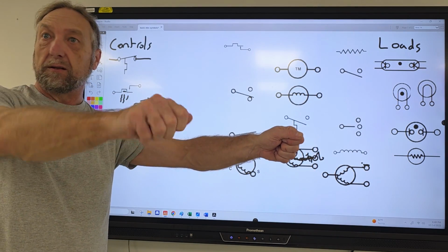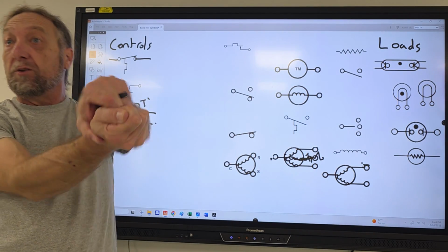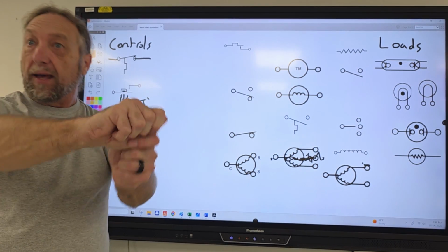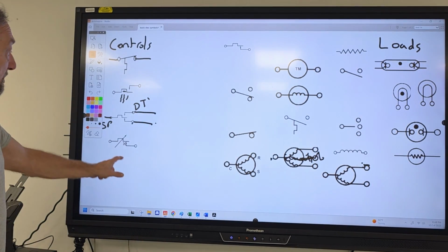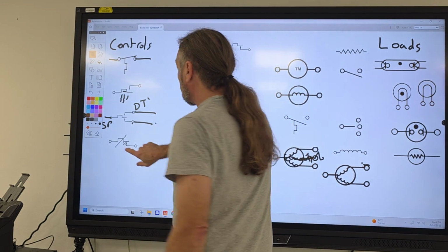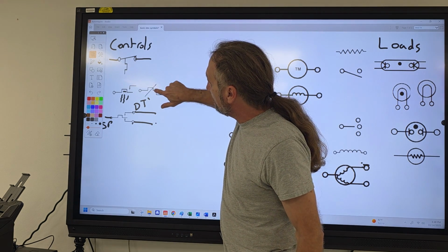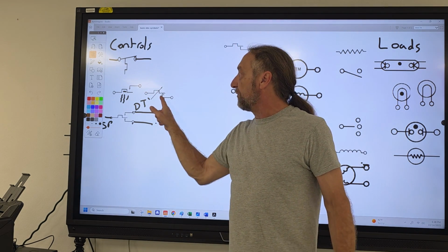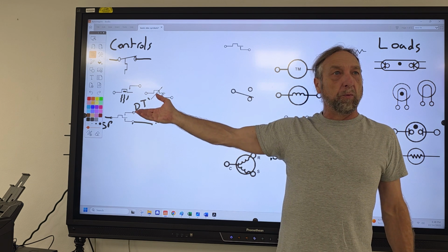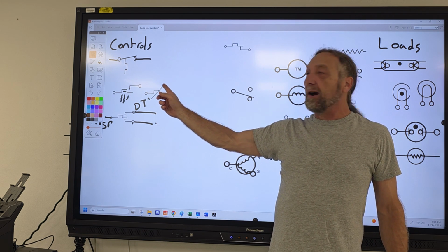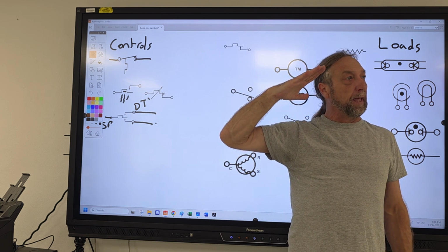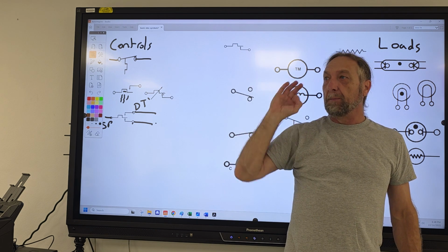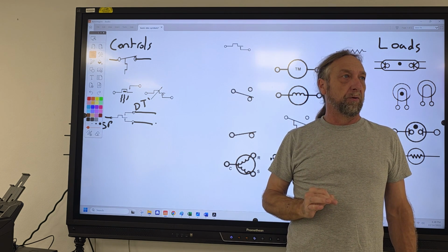That's your thermostat. You can put it to 300, you can put it to 500. And that's what adjustable means. Now this thermostat is pretty much the same as this thermostat as far as one's normally open, one's normally closed. But the arrow at a 45-degree angle through any part means that part is adjustable.